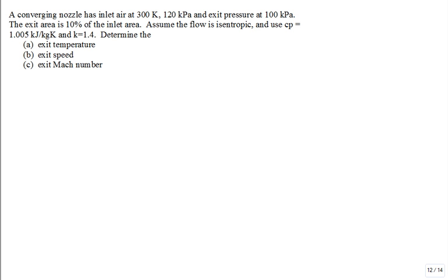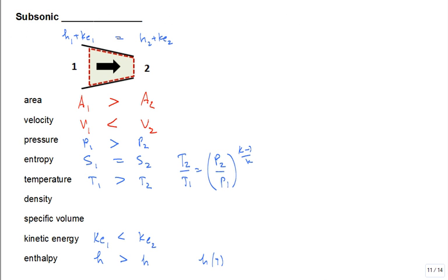I have one question. Why is P1 more than P2? Even if it's 1, it's going to be equal. You could have them equal, but then how is the flow going to go from 1 to 2? It's a nozzle. Typically, P1 is greater than P2. At the back of that jet engine, we only want the turbine to have a modest pressure drop across it, so we have a high pressure to push it through the nozzle to get it to go out at high speed at the back of that jet engine. So no, P1 higher than P2.